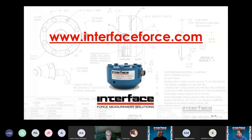Also, I see a question about assuming that all LCs are intrinsically safe. They are intrinsically safe devices, but anytime there's a hazardous location or intrinsic safety requirements, by all means, please review that with the application engineer. As you can understand, it's one thing to look at just the sensor, but you need to factor in all aspects. And again, given that these are typically working off of 5 volt, 10 volt, you need to look at all aspects. So again, anytime there's intrinsically safe requirements or it is a hazardous location, getting to the specifics of what the requirements are is typically the best way to handle that.